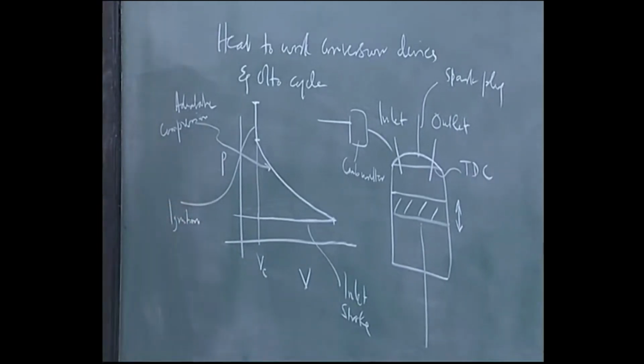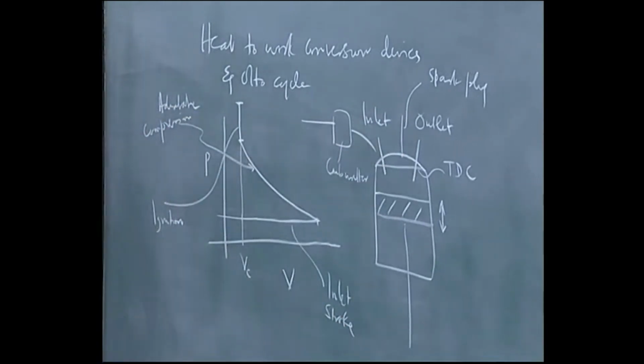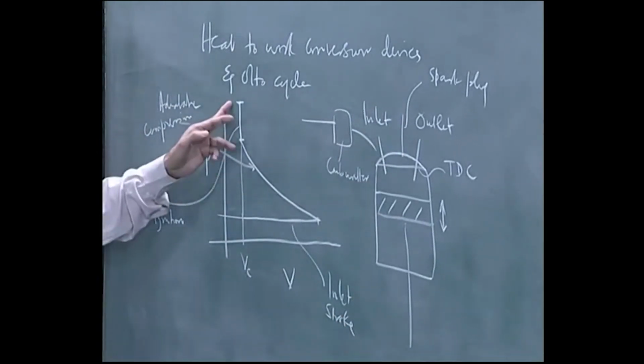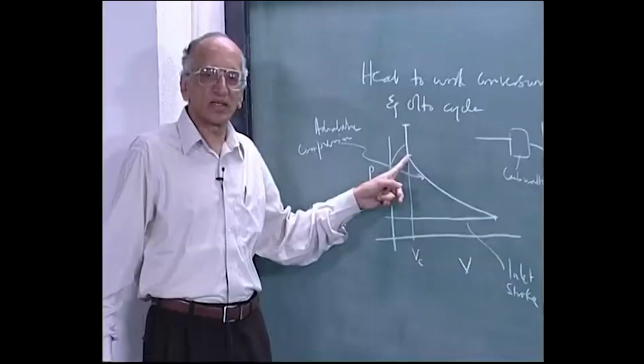The ignition is so rapid that the piston that comes up to the top does not move back during the time of ignition. The time of ignition is really small, so effectively it is constant volume ignition, that is the characteristic of the Otto cycle. As far as thermodynamics is concerned, this is where the reaction occurs.